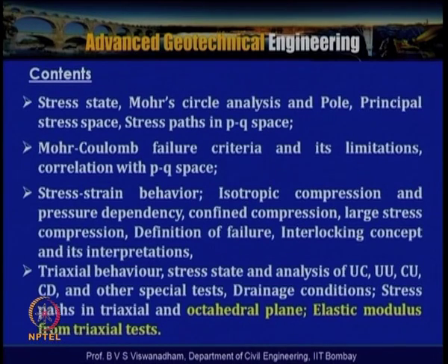In this particular lecture we will concentrate on the octahedral plane and octahedral stresses, and the interpretation of the elastic modulus from the triaxial test. We all know that the failure criteria used in soil mechanics were actually deduced from the mechanics of advanced materials.